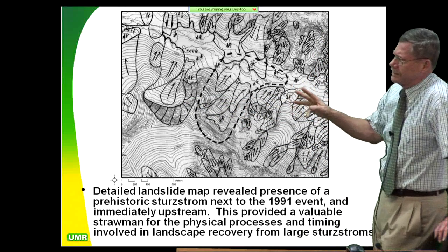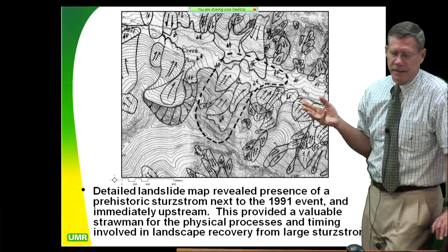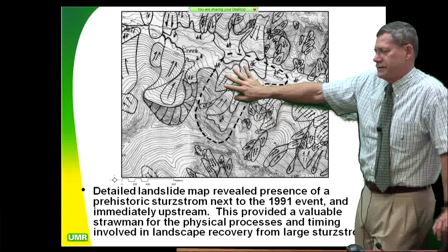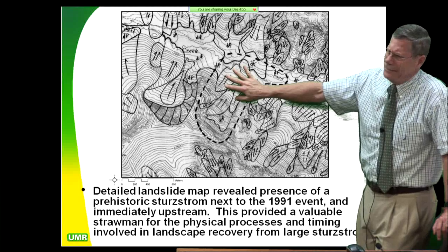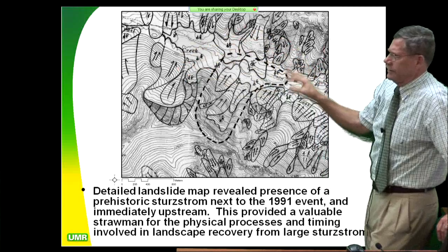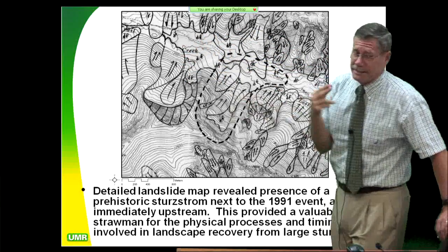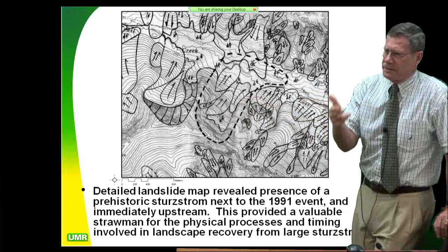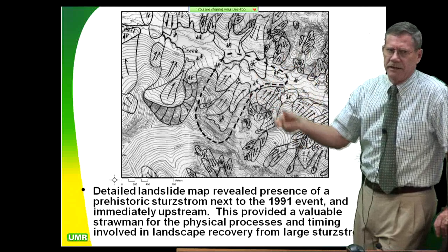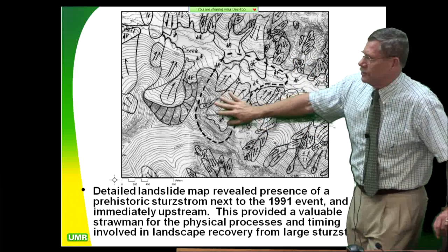When you're doing studies like this, you're always looking for what we call in geomorphology analogs. So if your client's asking you, what does the future hold for this? You can't answer that. How do you know what the future is going to hold? What you have to do is find an analog somewhere nearby that's very similar, and then go to school on the analog and try to date it. How old is it? How is it weathered? When did it breach? Has it breached yet? Etc., etc. The analog's going to be your lab tests to give you your predictions on this.